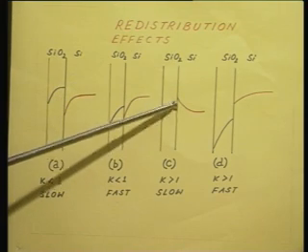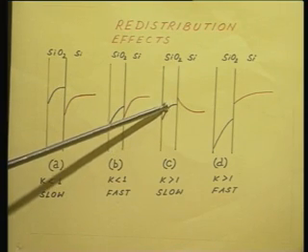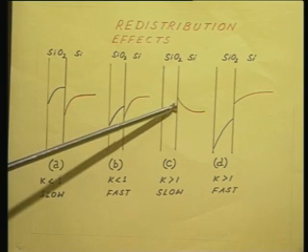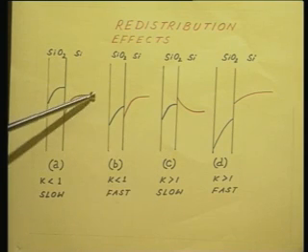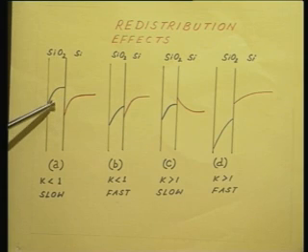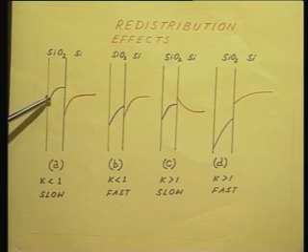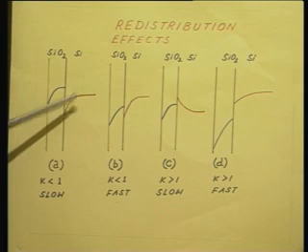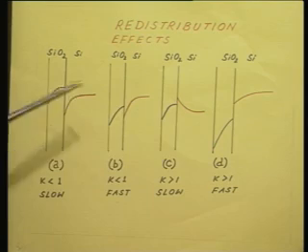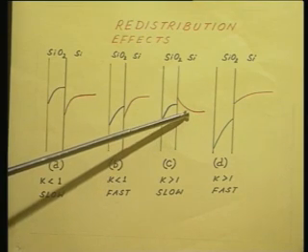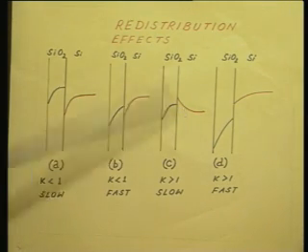That is, it stays more or less constant over a considerable distance, and only towards the surface it starts falling. The important difference between A and C is in the silicon dioxide interface. In one case, the boron concentration at the interface is low on the silicon side, the phosphorus concentration at the silicon dioxide interface is high on the silicon side. That is because of the difference in the values of K.